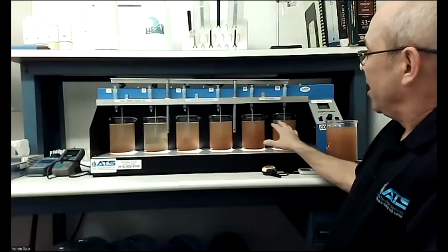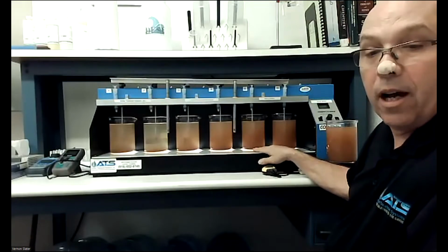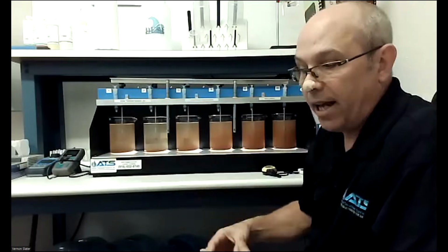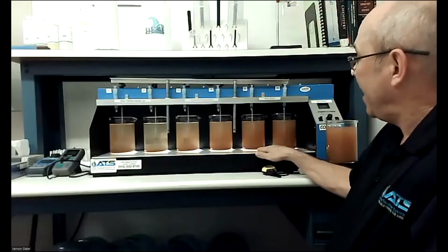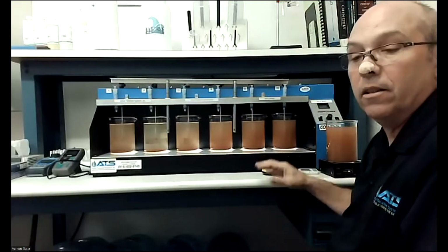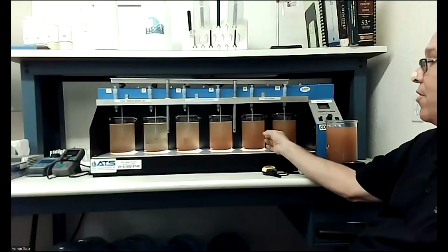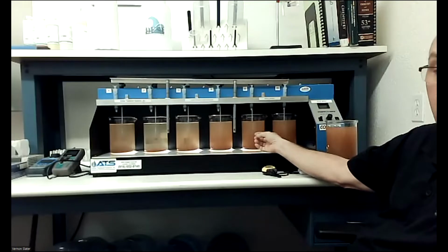What happened down here by putting more product in? I overdosed. I took an anionic problem that we had when we started, a bunch of anionic particles fighting themselves. I added enough cationic material to now cause a cationic problem, and their settling will not happen. So this could be caused from pH. You'd want to check your pH. It also could be caused from overdosing, and that's where a jar test comes in.